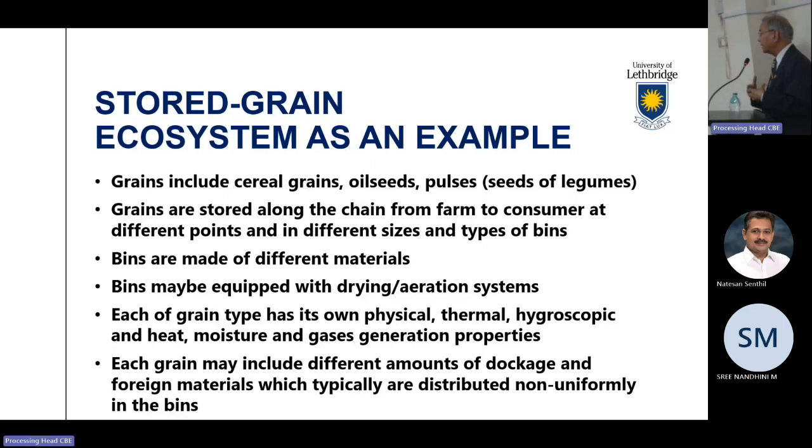When they are in dry conditions, they flow freely, and they are granular in structure. When you fill them in a storage structure, all of them exert a pressure on the wall system, whereas water, for example, does not exert friction force vertically downward on the system. All fluids, including water or liquids, exert stress along the circumference of the structure, but grains also apply physical force or friction along the walls. So that's what grains are referred to as.